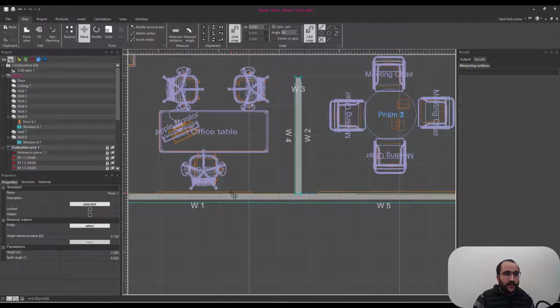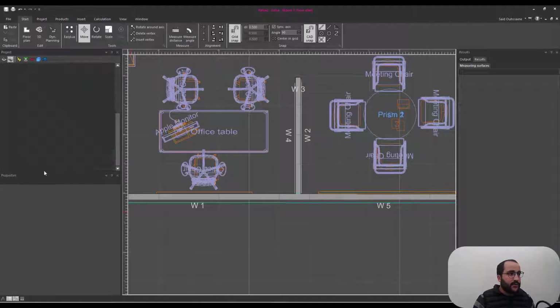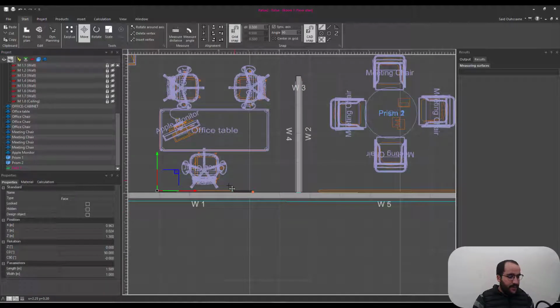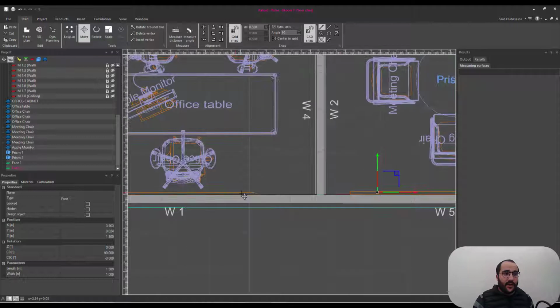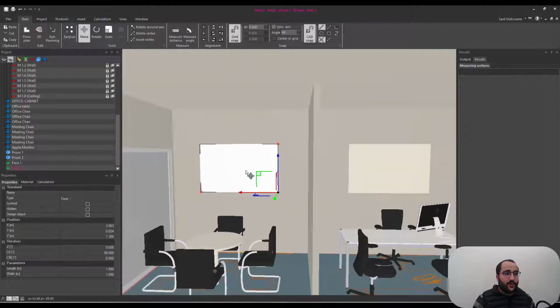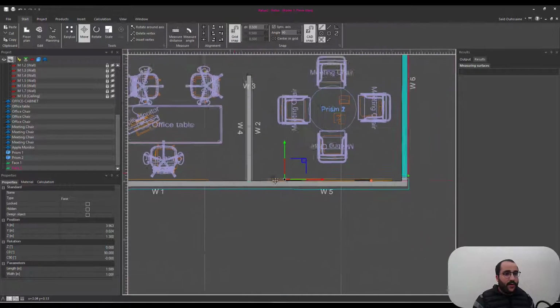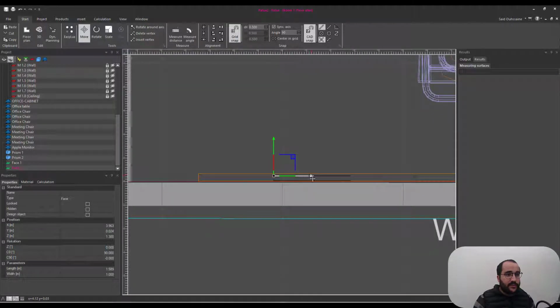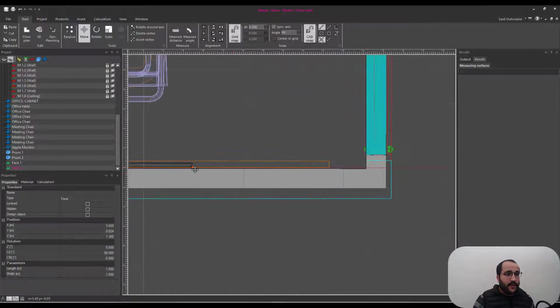I'm going to select it, go again to this face here, press Control, and drag this new element here. I still have the first one, but then I have a new one here. Now I can press Shift to be free again, because I have activated this grid snap, and then I can scale this like that.